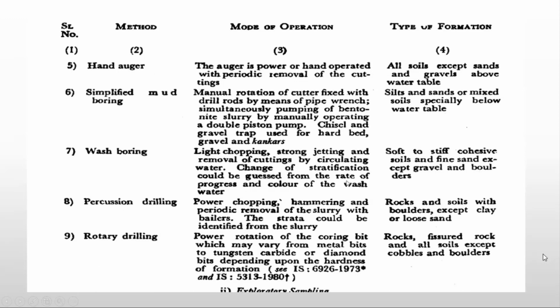Similarly, for others: where you will use hand auger, simplified mud boring, wash boring for soft to stiff cohesive soils and fine sand except gravel and boulder, and rotary drilling for rocks, fissured rock and all soils except cobbles and boulders.